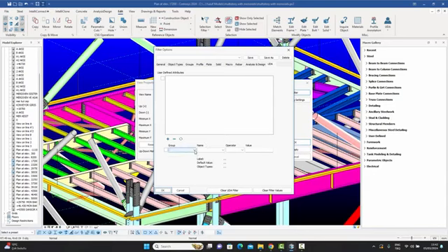So for example, if I were to go down here, I've created these two group captions, one was called finish, if you remember. And inside finish, we had two different attributes, the surface finish and the sandblasting type, which I had added later. Let me go to the surface finish one, because it was a text list, if you remember. Let me select the equals operator, and because it was a text list, I don't have the ability to just write anything random, but I have to choose from the given texts which were already entered. So let me choose the fire resistant paint over here.